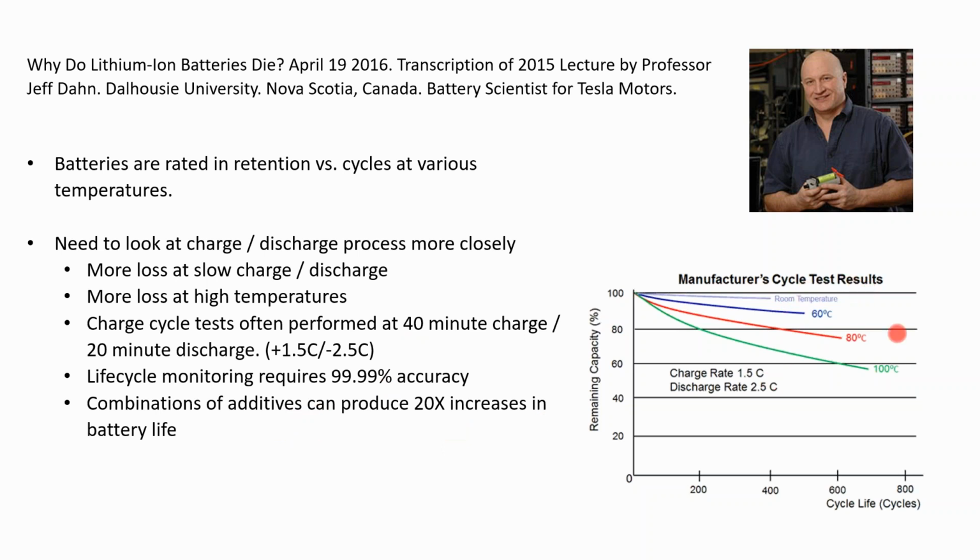Okay, so how are batteries impacted by temperature? Well, the hotter a battery gets, the more the remaining charge is affected. What we see here is a room temperature battery, with cycles and remaining capacity. If the battery is operating at a higher temperature, we actually see some degradation in its remaining capacity. So hot temperatures are bad for battery life.